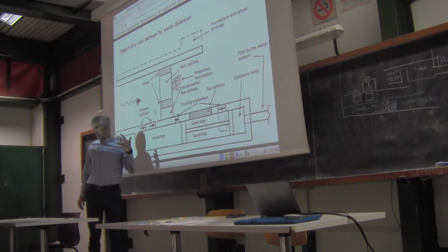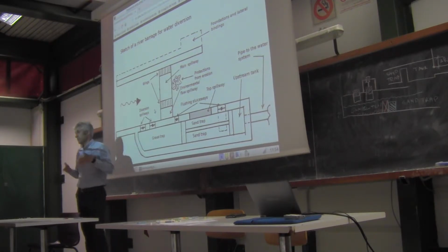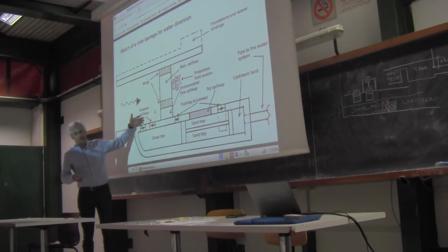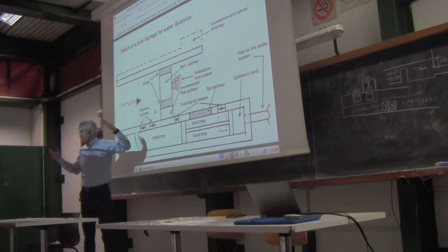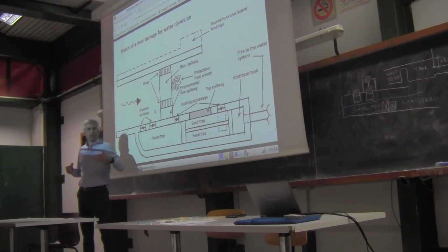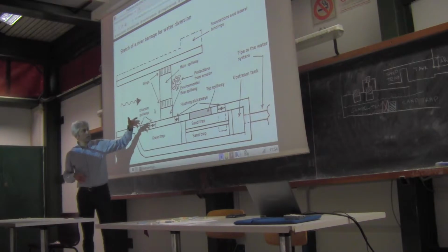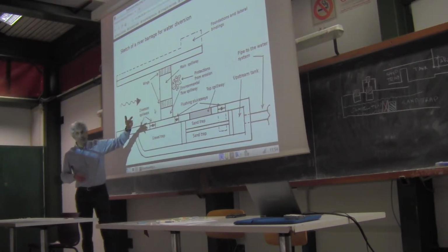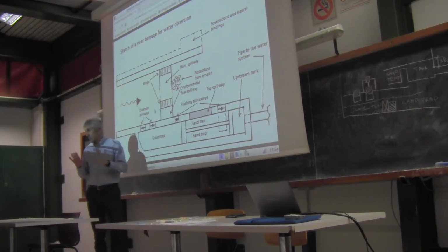What happens over a spillway? Over a spillway, if you don't have any water, you have a dry spillway. Okay, perfect. And then let's suppose that some water starts coming from upstream. And let's suppose that here, upstream the structure, it's empty, it's dry. Okay, water starts accumulating against the structure. And then when water reaches the level of the environmental flow spillway, we start seeing some flow moving downstream. Good.